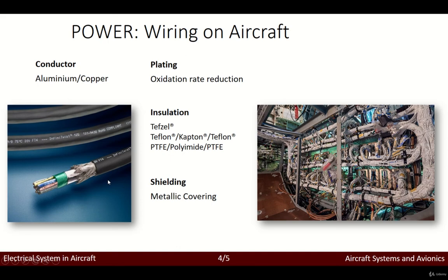Right, so this interference is caused when electromagnetic fields, as I said before, maybe sometimes also radio waves, induce high frequency voltage in a wire or component. Of course, this would be a problem in our cabling, and the induced voltage can cause system inaccuracies or even failure. So basically we also need shielding for all of our wiring on aircraft.